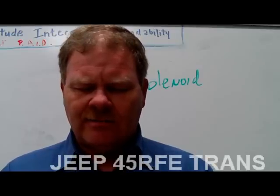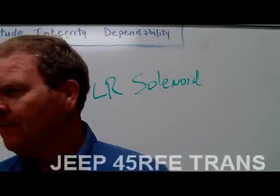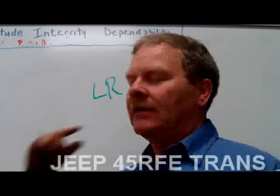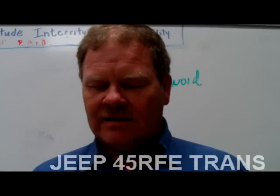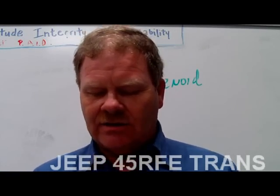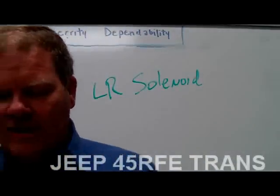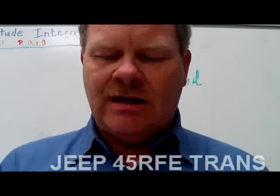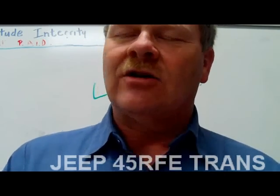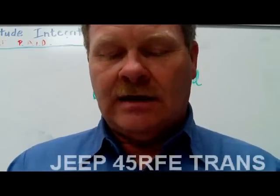If the transmission controller sees certain problems, it shuts off power to itself. Oh my goodness, it cuts its own throat. I see problems, kills itself. The loss of power to the TCM will result in limp-in mode operation. So what is that? When the solenoids are de-energized and revert to their default positions during limp-in, if the shift lever is in drive, the transmission will be in third. If it's in manual second or low, the transmission will be in second. So you can shift it manually if you have to. That's the cool thing about that.